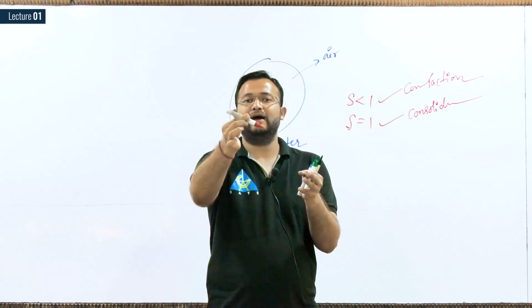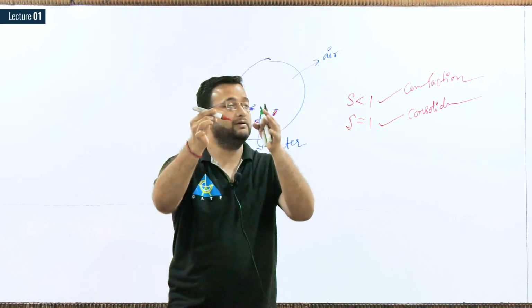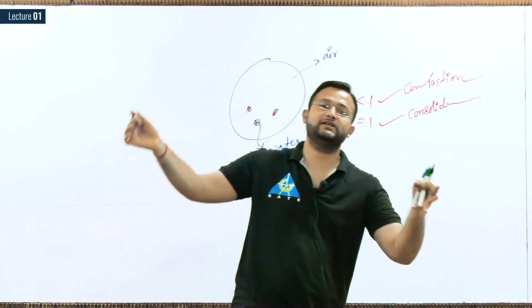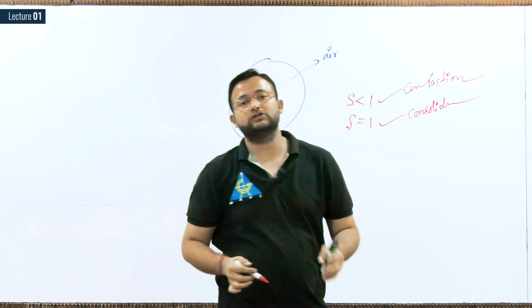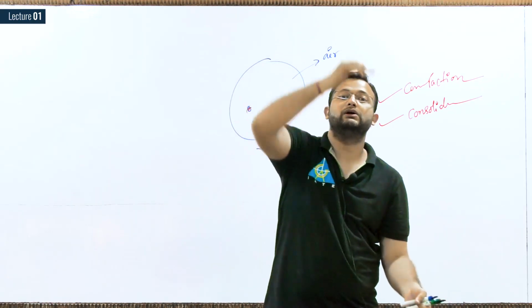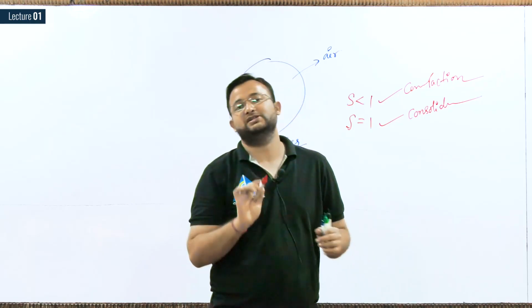In that case, what will happen? Your footing will be subjected to moment, your column will be subjected to moment, your entire building will be subjected to the moment, and the moment will cause your building to rotate. Your entire structure will get overturned and the building will collapse because of differential settlement.